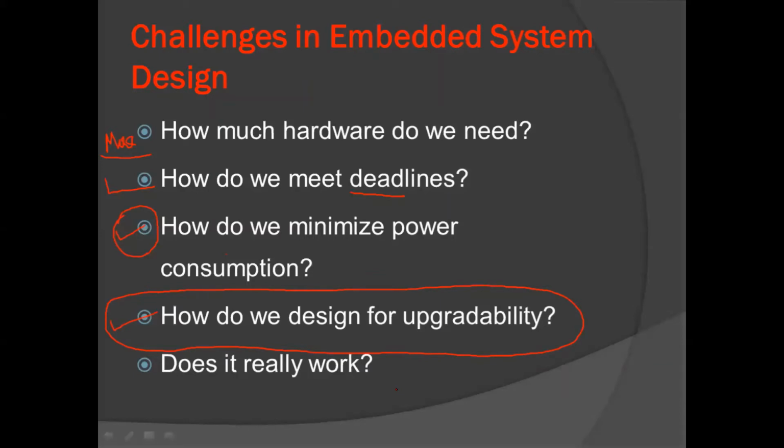As soon as we come to a conclusion of a NodeMCU, and if someone says, I may need one more channel in the future, right? Currently, we are having two channels, that is temperature and humidity. But what if I need one more channel in the future? And let's say I may need an extra analog channel in the future. Okay, let's be precise about that. Currently, NodeMCU, what you see, is having only one analog pin, that is A0, right?